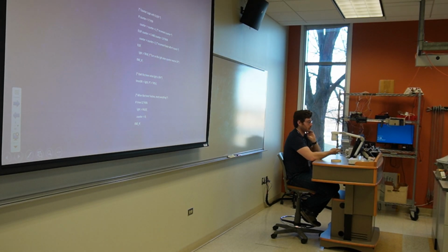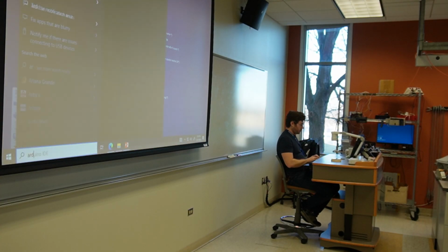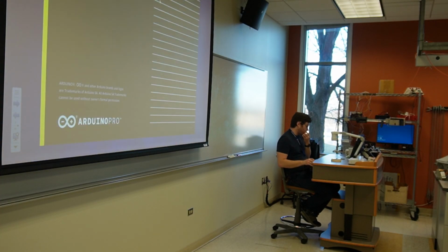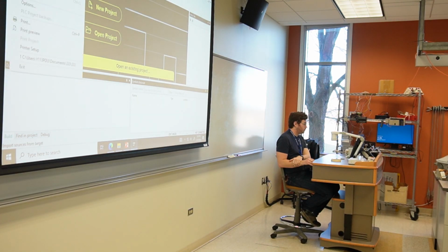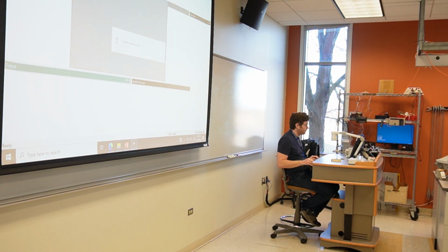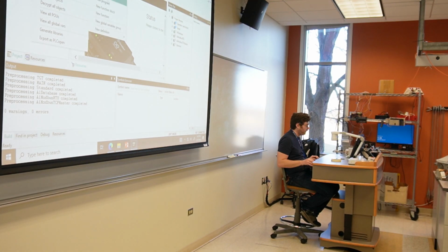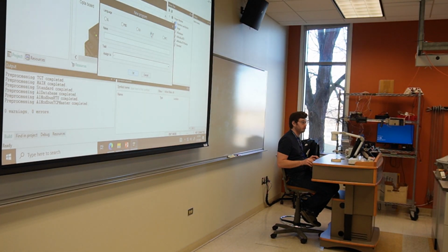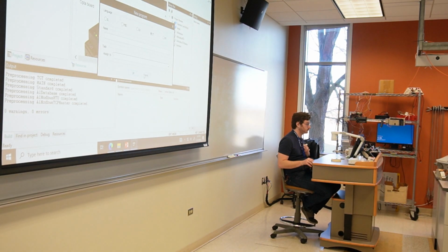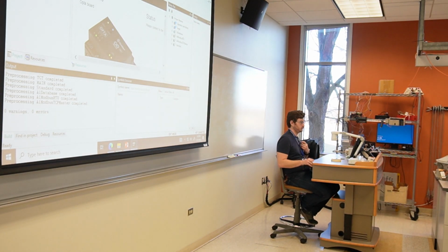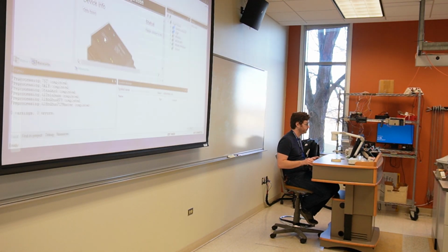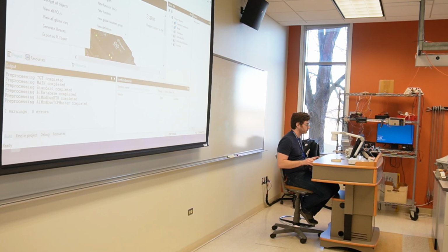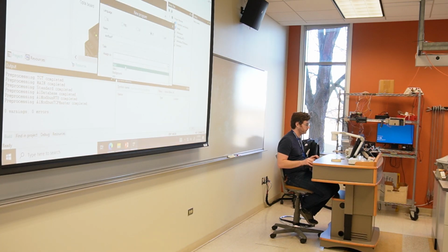Structured text? Sure, I could show you that. You're going to go new project, and right click that, add new program, and then you want ST for structured text. And make sure to put it in the fast task group too. Right, fast task group.